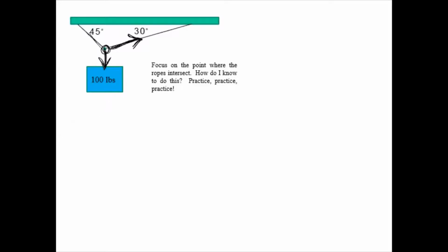Likewise, the tension over here in the 45-degree angled one is that direction. Again, imagine cutting the rope here. What happens? The weight would swing this way. So again, that tension is kind of holding the block or the knot, if you will, up and to the left.